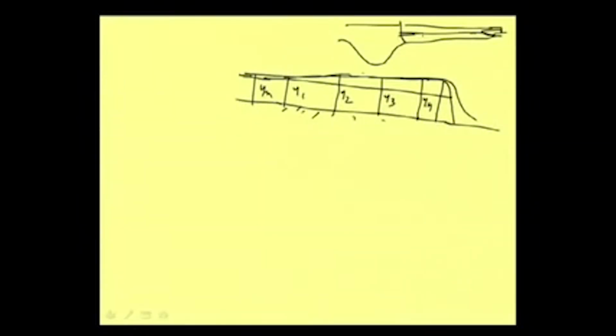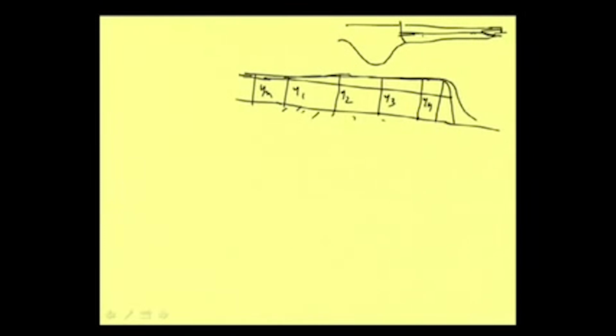Well, in a canal also, which is made for agricultural purposes, we sometimes increase the depth to carry water to the side channel or side feeder canal or field channel. So, that way also this water level is increased and we can get a gradually varied flow like that. Again, this gradually varied flow can be of different types, that we will be discussing later, but this is one kind of gradually varied flow. And this sort of curve is a rising profile, it is gradually rising. So, this is rising, and this has another name that we call a backwater profile.